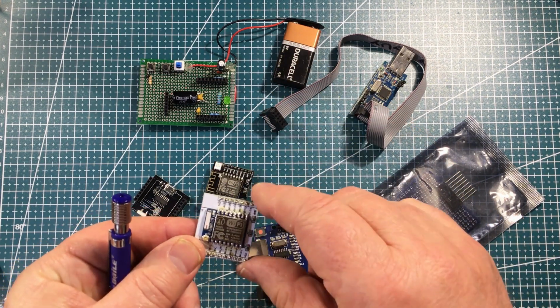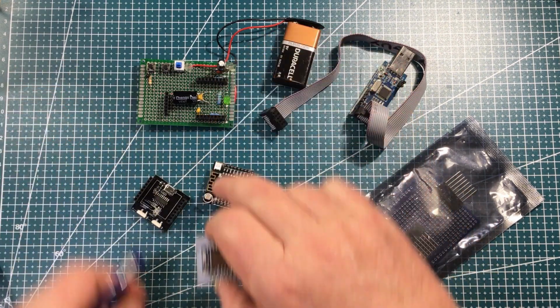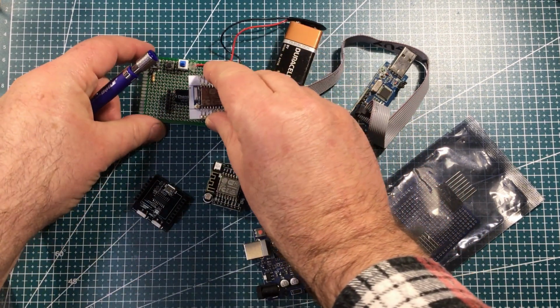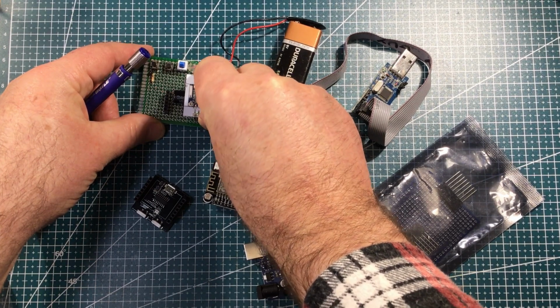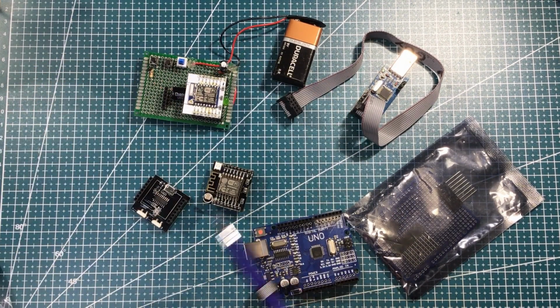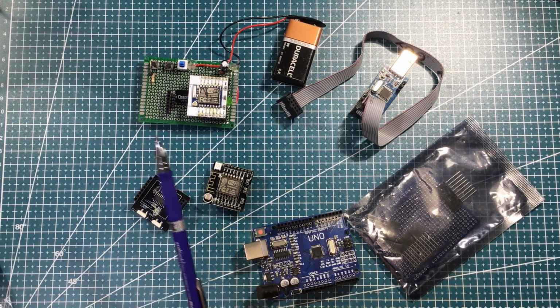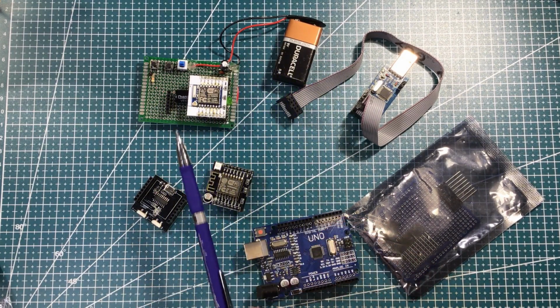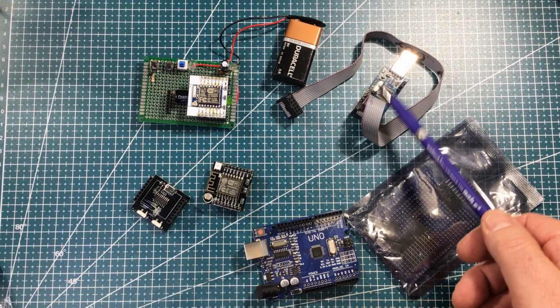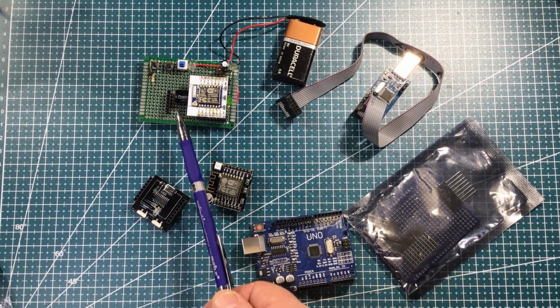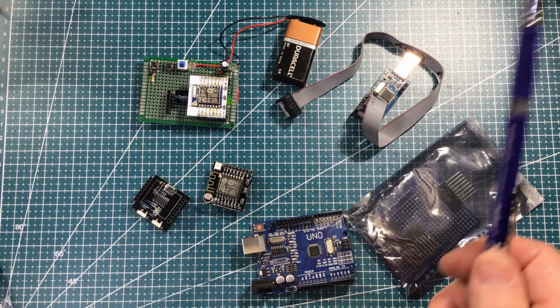So this is a typical arrangement here. You've got your ESP8266 on an adapter board, and it just sits in this cradle here. And then you've got your usual connections to TX and RX, a big stonking capacitor there, and a few buttons, and even a separate power supply. And then your USB ASP just connects up to these pins here and you are good to program.